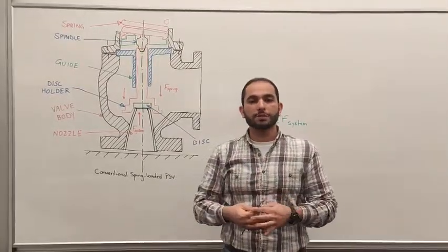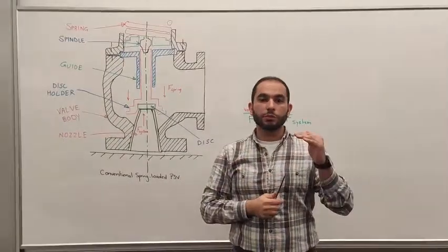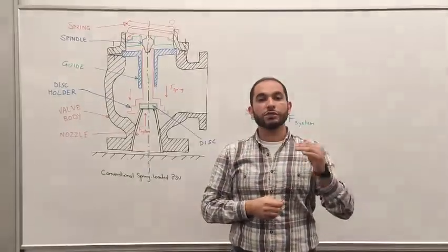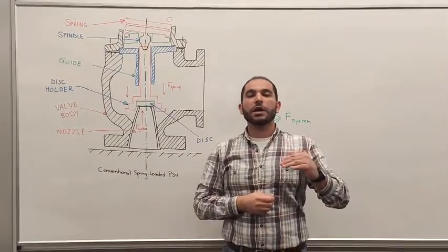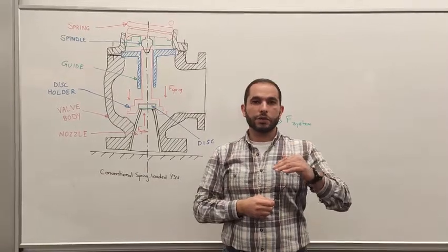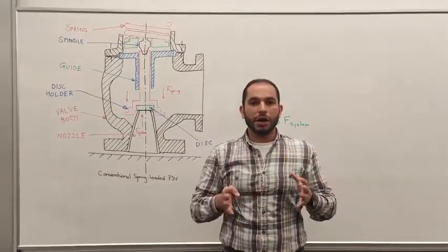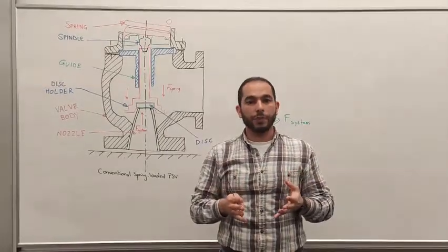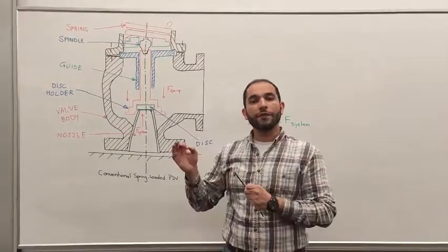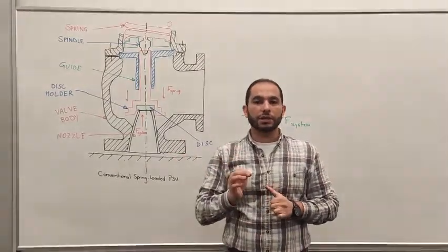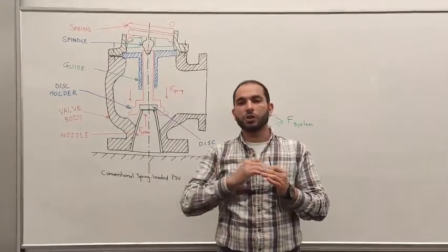In other words, the PSV is required to open at a certain system pressure, which is very important, because if the system pressure increased or surpassed that value, the integrity of the whole system would be impaired. So it's very crucial to have that PSV very accurately set in order to open at that certain value and not to exceed it.